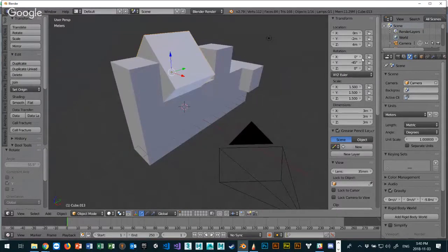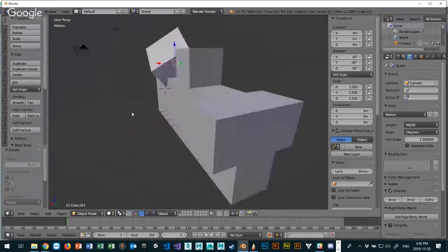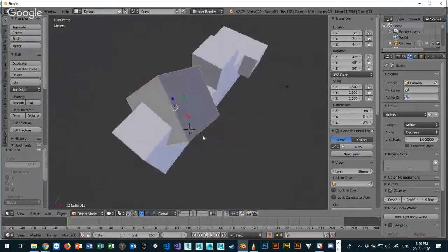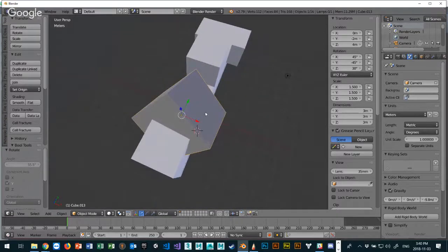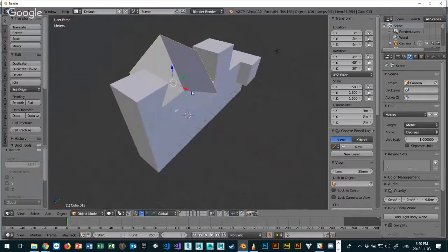If I want to rotate it across the X-axis 45 degrees as well, I can just go here and put negative 45, or I can go to 45. It'll look the same. What about if I want to change my Z-axis by 30 degrees? Let's just put 30. Now you can see that the cube has been rotated across the X, Y, and Z axes in a non-uniform fashion. So rotation is R, scale is S, and G is move. Those three hotkeys you need to know.